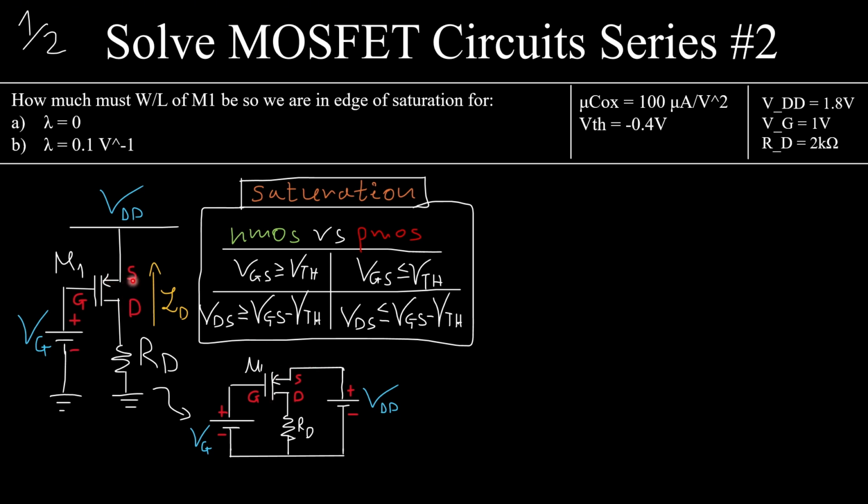And we also note that the arrow points towards the MOSFET. This means that the current actually flows like this, even though we draw the arrow of the current from here all the way to here. Why? Because the current, by definition, must flow into the drain, all right? And we will see later that the current has a negative value.